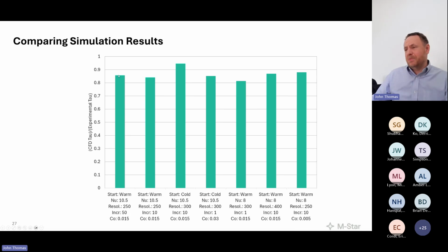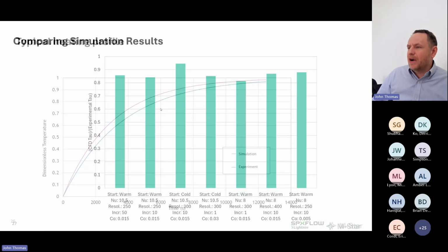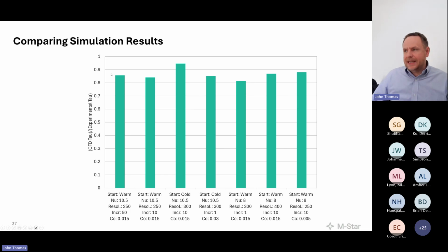And we can see here the approach is surprisingly robust. If we compare the predicted, I can extract a tau. This is just first order. I can extract a tau from this. So if I compare just my taus between the measured versus predicted, I'm consistently within somewhere between 6 and 19% of what was measured experimentally. Interestingly, I'm systematically below, which says it could be an experimental thing or a simulation thing. It's obviously a simulation thing, but it could be something we're not accounting for in terms of our fluid properties. But either way, the headline is that we're nailing it, right? With one semi-empirical model at industrial scale, using just operating conditions, we predict the response of a vessel as well as temperature variations within it.